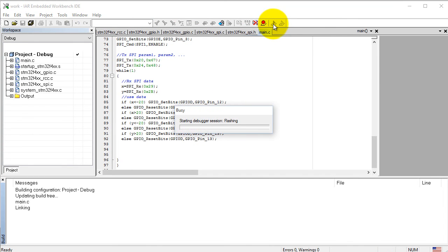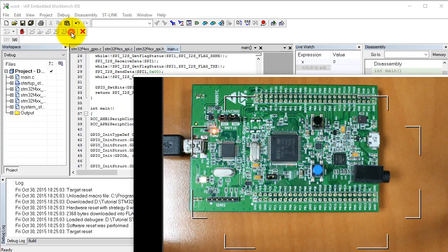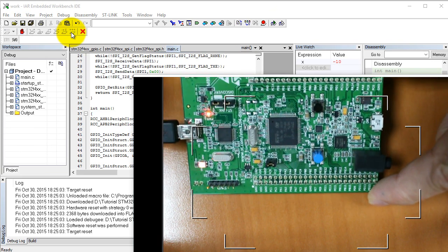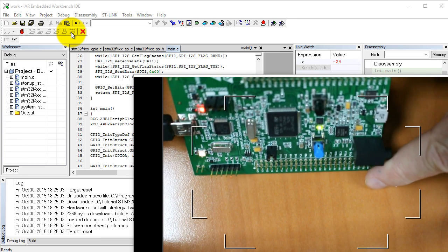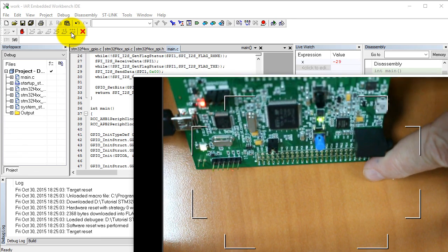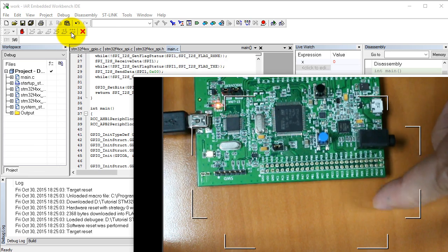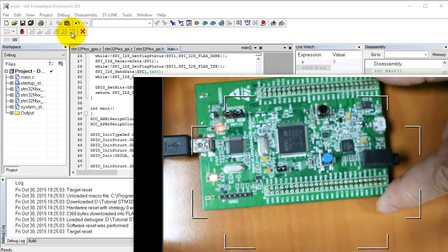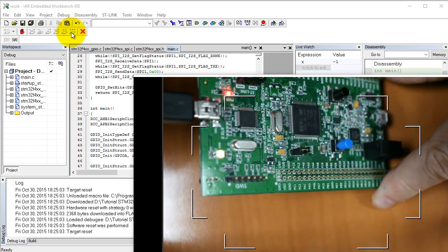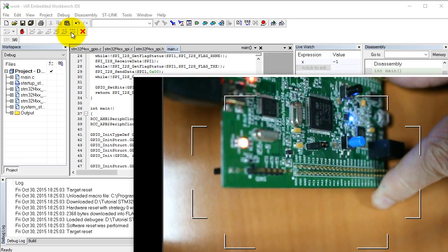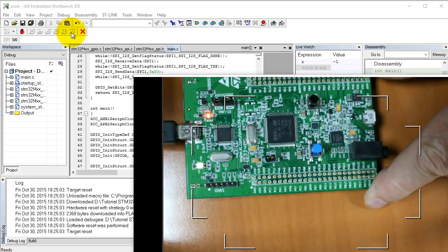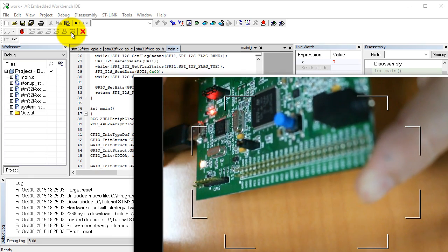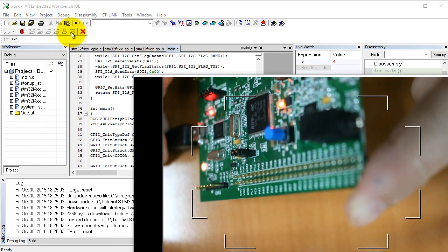Now, if we compile, flash and run the program, we notice, as expected, that the board has to be inclined at a bigger angle to turn on the corresponding LEDs, because the default full scale was plus minus 2G. The program is fairly simple, as it uses polling for detecting the end of any transaction with the accelerometer, which is suitable for most applications.